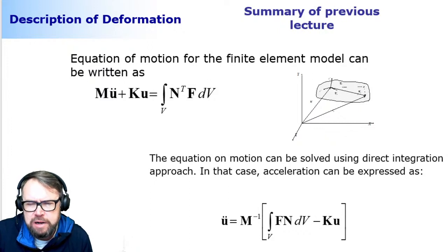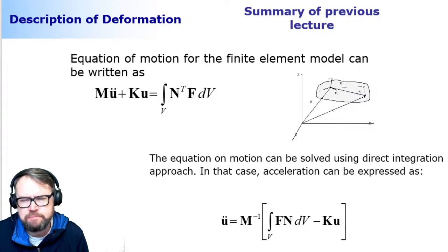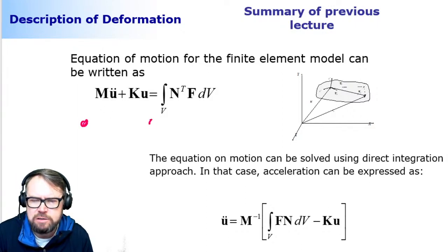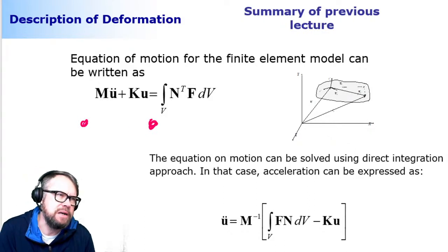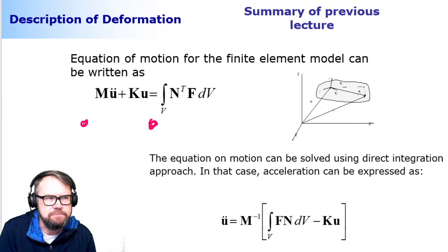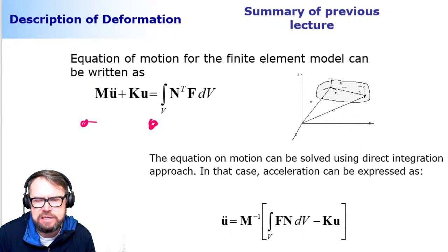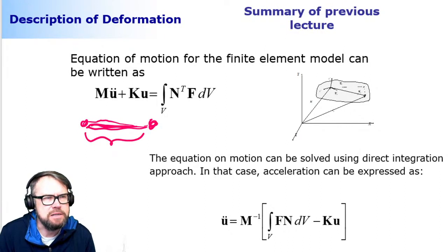Now, what happens in finite element modeling is this: you get started by first selecting how many nodes you would like to describe, or more specifically, what is your number of degrees of freedom. Once you get your number of degrees of freedom, then you express your element behavior by using polynomial expansion. But polynomial unknowns are a little difficult to deal with, so you want to convert the unknowns to be expressed by using nodal degrees of freedom. Once you have the nodal degrees of freedom, then you get these shape functions, and the shape functions are telling you how the particles between the nodal locations are expected to behave.